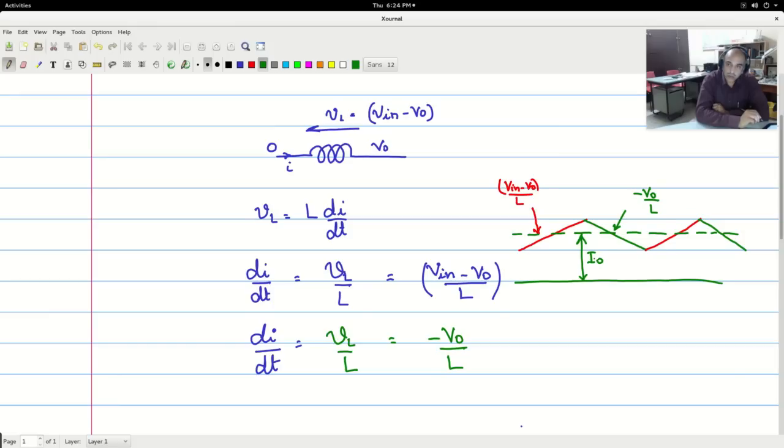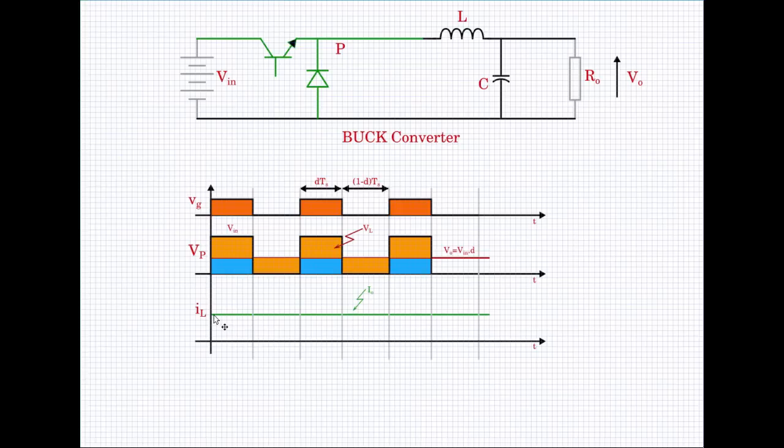And the ripple value, the one with that component with zero average, will flow through the capacitor. So through the capacitor, the one marked like this is what is going to flow. So this is what we can expect, and let us go back and have a look at the circuit. So the average value of the inductor current is I naught, and that is what will go through R. The ripple component of the inductance will go through the capacitance, and there will be a ripple component here.